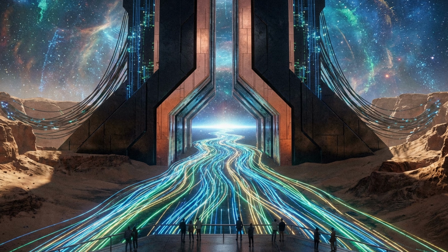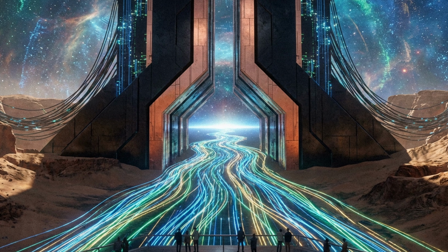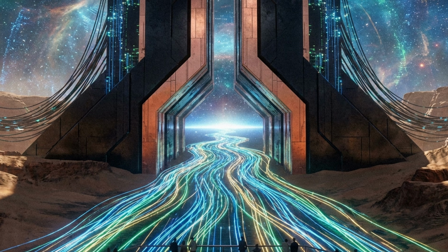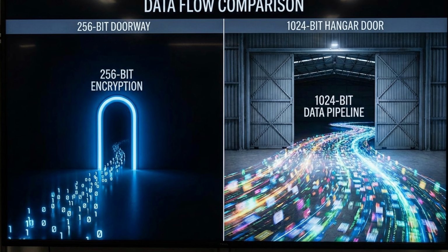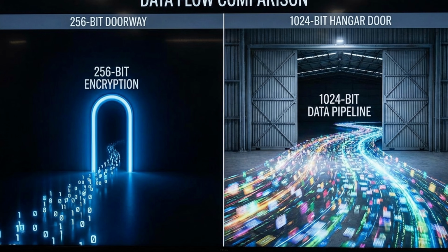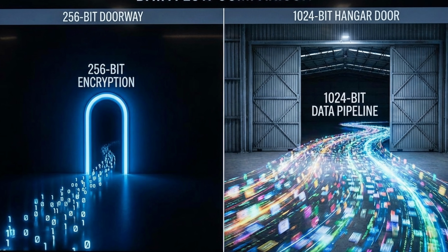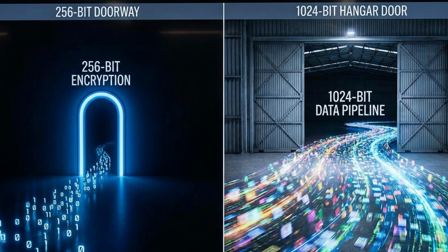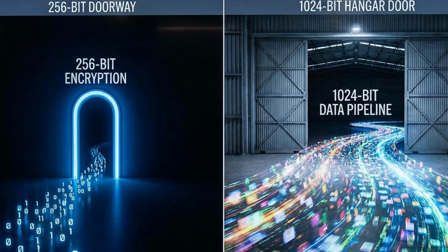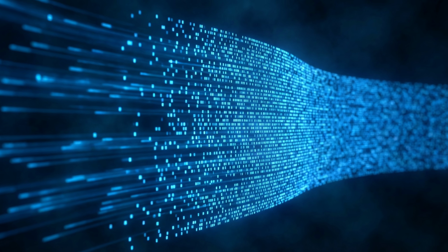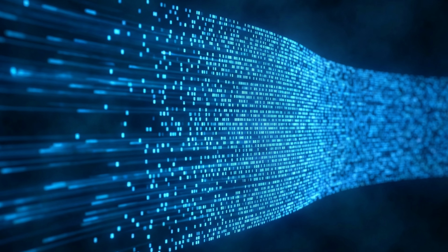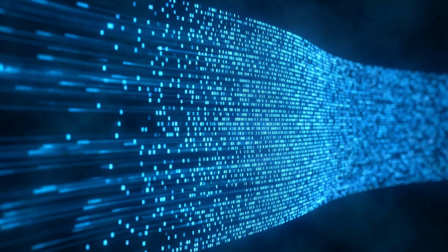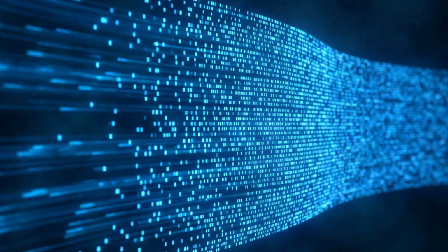The defining characteristic of this technology is its ultra-wide memory interface. Where a standard memory interface might be 256 or 384 bits wide, high-bandwidth memory utilizes a massive 1024-bit or wider bus. This allows the processor to move gigantic volumes of data in parallel, achieving enormous bandwidth even at lower memory clock speeds.